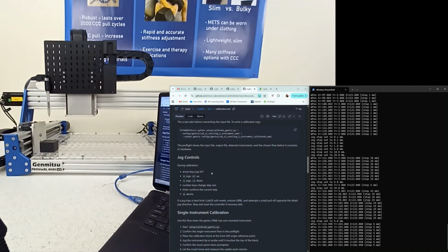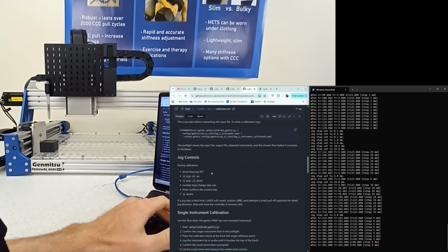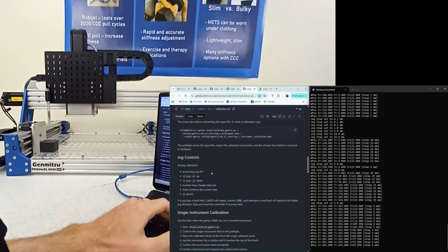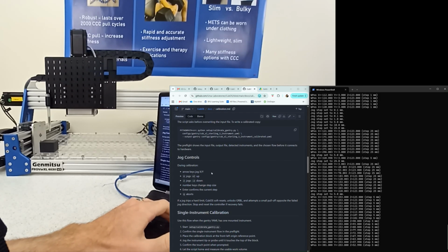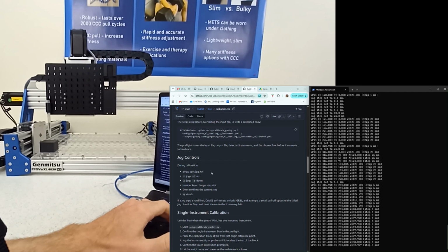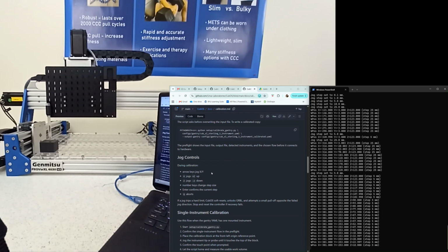Okay. Let's keep moving. Okay, it might have come unplugged. The Z limit. Yeah, the Z limit did come unplugged. That's not ideal. Okay, I might mess things up. So there's a problem with the hardware build with the wire, especially in the Z direction. It can't go as far down as it needs to. Let me see if I can fix that, and I will be right back.